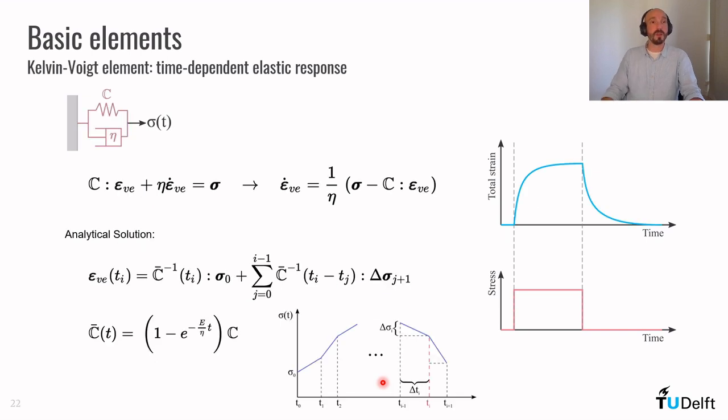Okay, let's move on. Now we have the Kelvin-Voigt element. We need to know how to compute the deformation at this element when we apply a certain stress. As I've mentioned before, we assume quasi-static loading condition, which means that the external load is in equilibrium to the stresses on the spring and the dashpot.